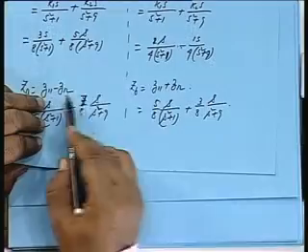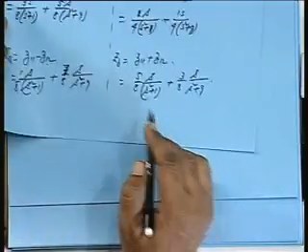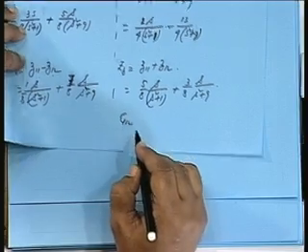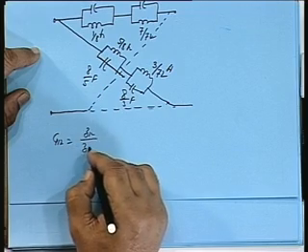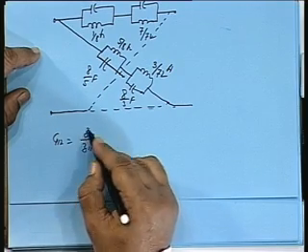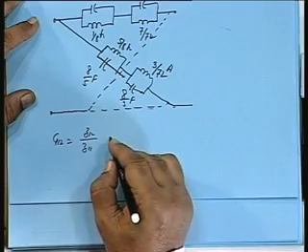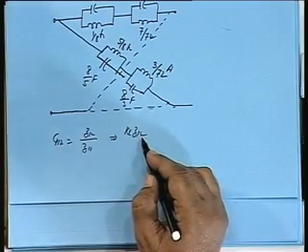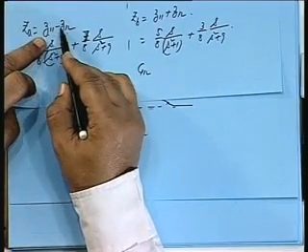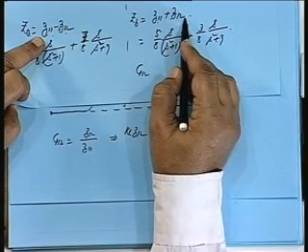Next we go for a situation when Z11 minus Z12, Z11 plus Z12, these things are made. Basically Z12 contributes to the function G12, is it not? It is the G12 gain which will be decided by Z12 by Z11. Now I can always multiply this by a constant, because poles and zeros will not get disturbed by that constant. It is something like an amplifier we can put later on, which can take care of whatever gain is to be adjusted. So instead of Z12, sometimes we go for KL times Z12. If I make KL times Z12, then it will be Z11 minus KL times Z12, Z11 plus KL times Z12.